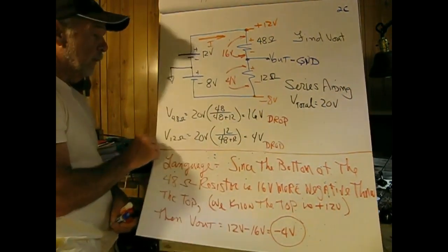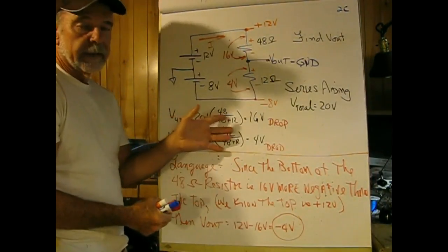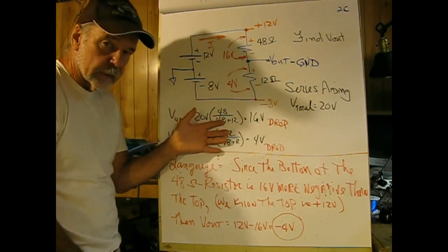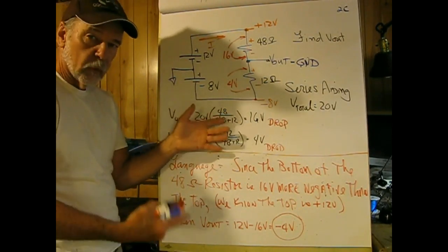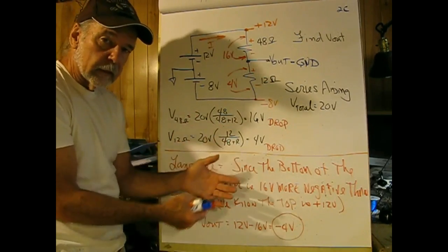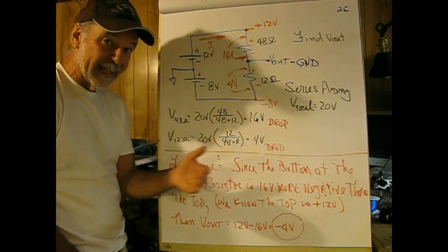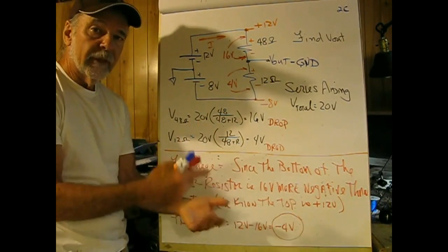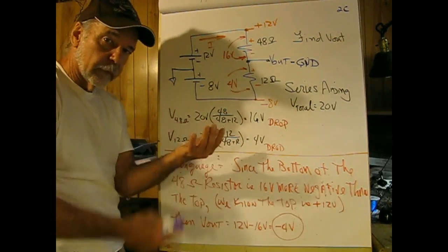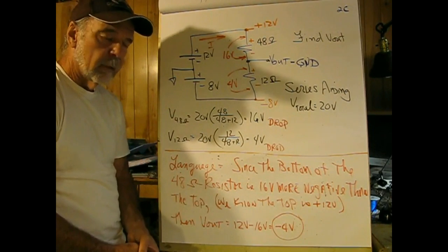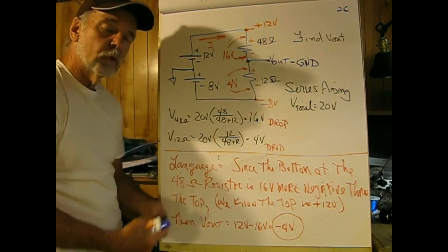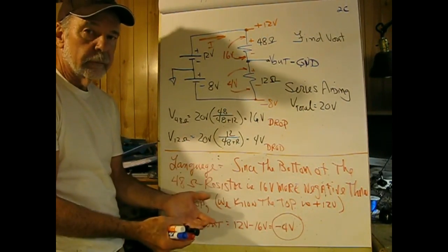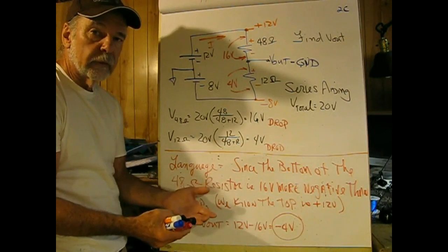Now, when it comes to that, some students plug and chug in calculators. And that's not a good idea. And the best example I can give is when I was adjuncting at Tri-C. It was an Electronics 1 equivalent course. A student correctly calculated the gain of a transistor amplifier to be negative 66, which means the output is 66 times larger, but it's inverted. The sine wave is going in the other polarity first. He built a lab, measured negative 3, and turned the lab in. No bells went off as to 66 theoretical, 3 measured. Nothing. Write it down, turn it in, go home.